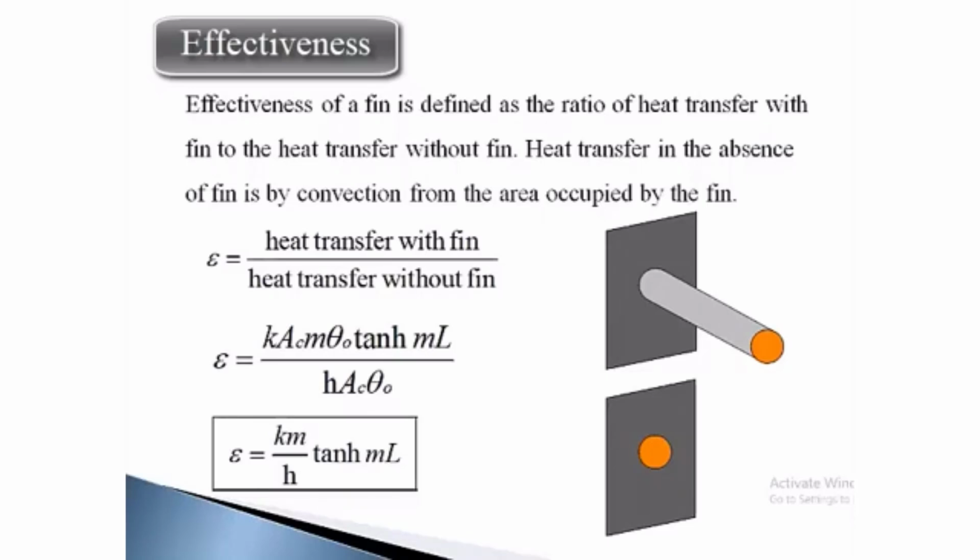You get the heat transfer through this kind of fin as kAc theta 0 tanh mL. That's what we have studied in the previous class.